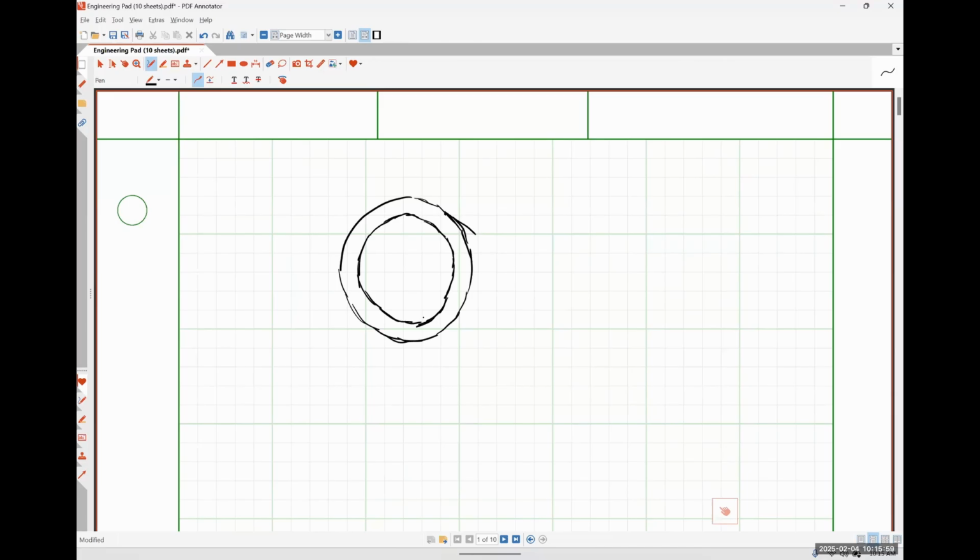So let's say that this was a 3-phase machine, okay? We might have an A phase over here. I'm going to do that in black, and I'm going to say that the current is flowing in on this guy, and it'll be flowing out on this guy. So this is our A phase, and we've got 2 poles, one positive polarity pole for our coil, the other one the negative polarity pole.